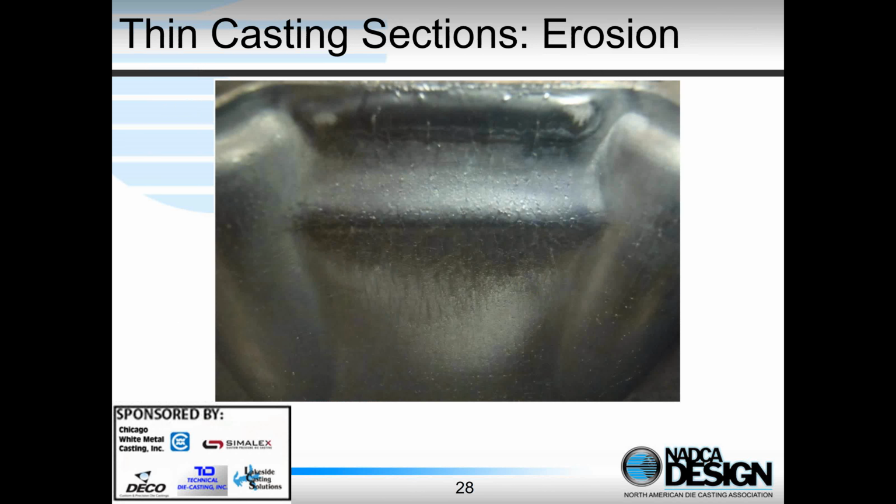Now, as I get very thin, 2 problems do show up. For thin sections, generally the metal velocity, the velocity we're filling the die, tends to be very high, and so we can get erosion of the die steel, of the casting die itself, and that's what we're showing here in the photograph. We can see here that the surface of the die is not as good as it is comparing it to areas over here. And what's happened is that in this area the liquid velocity of the liquid aluminum, for example, filling the die is very high.